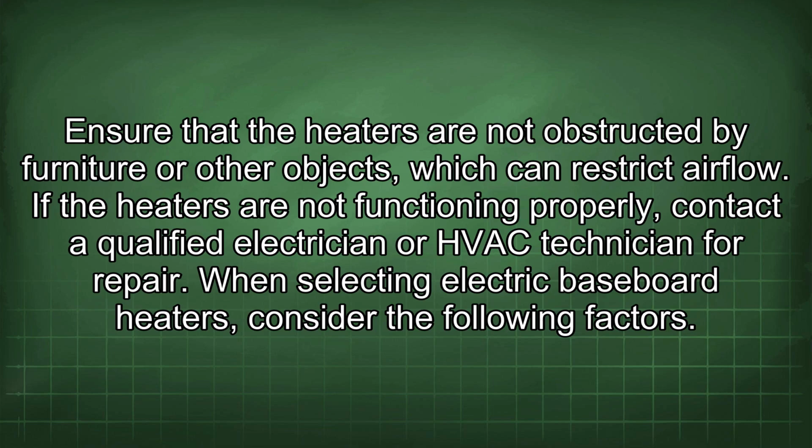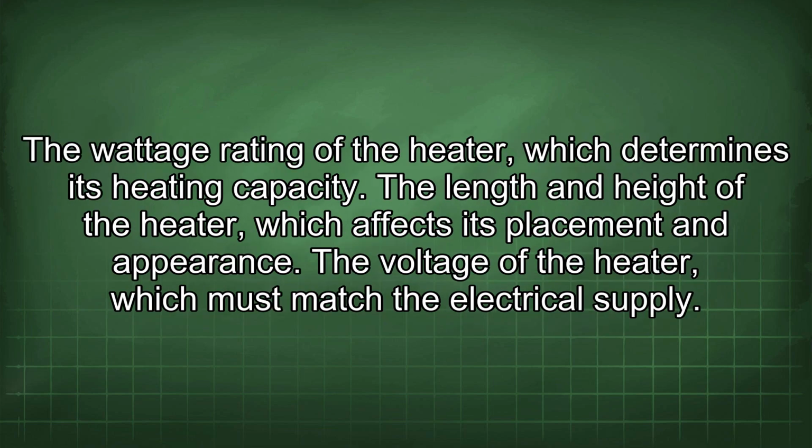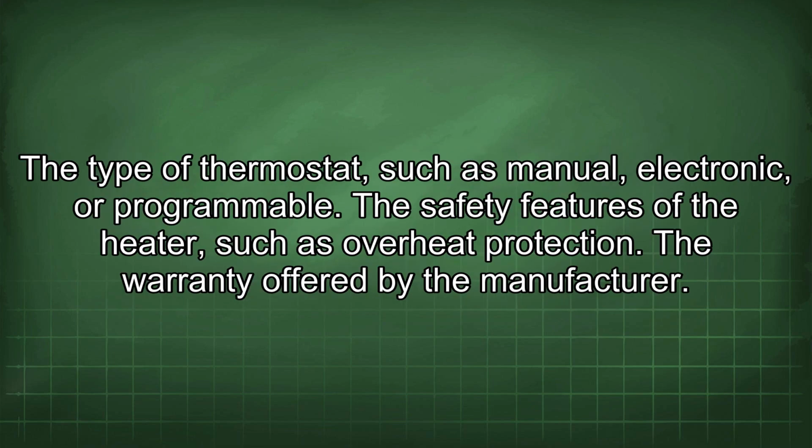When selecting electric baseboard heaters, consider the following factors. The wattage rating of the heater, which determines its heating capacity. The length and height of the heater, which affects its placement and appearance. The voltage of the heater, which must match the electrical supply. The type of thermostat, such as manual, electronic, or programmable. The safety features of the heater, such as overheat protection. The warranty offered by the manufacturer.